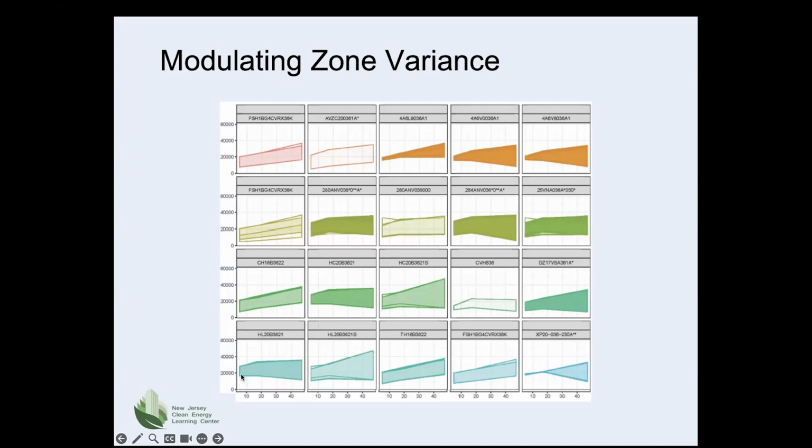So as a contractor looking at various makes and models, you want to be able to meet the heat load at low temperature, but depending on what the load is at low temperature can depend on what heat pump you select. If you're in a warmer climate, as an example, a heat pump like this one on the top row in the middle, it doesn't have much low-end capacity, but you may not need it.